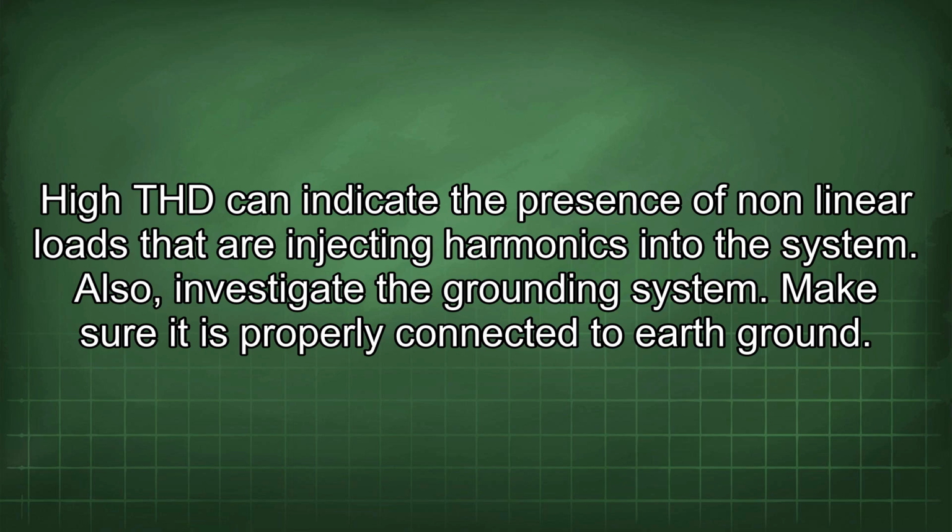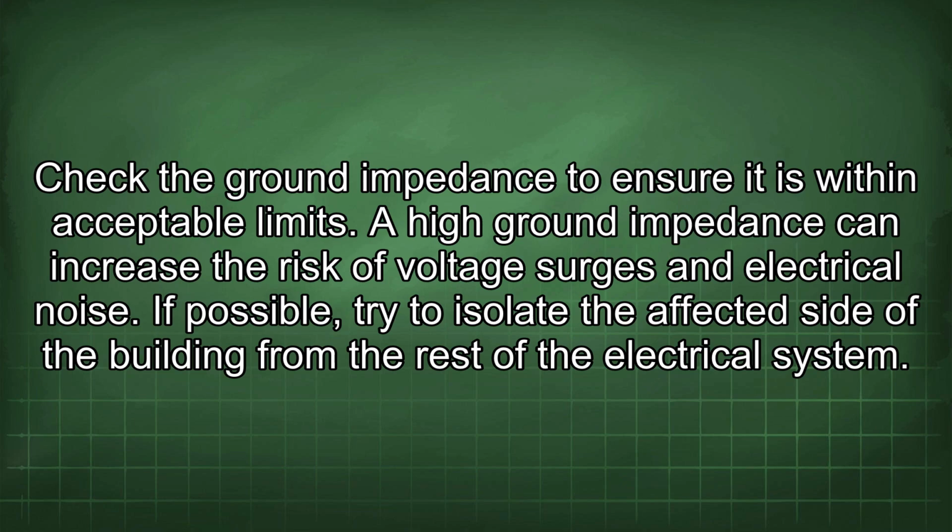Also, investigate the grounding system. Make sure it is properly connected to earth ground. Check the ground impedance to ensure it is within acceptable limits. A high ground impedance can increase the risk of voltage surges and electrical noise.